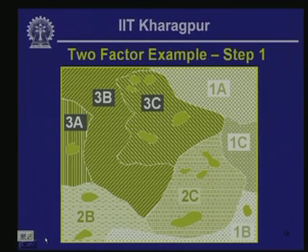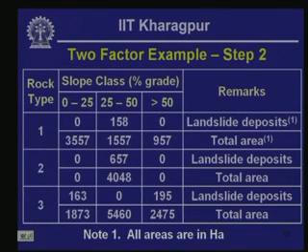Okay. So, then what we do out of the data presented on a map like this, after we superpose the areas that are affected by recent landslide activities, is prepare a matrix such as that presented here. For example, here we have 3 different rock types and 3 different slope classes, as we have seen earlier.